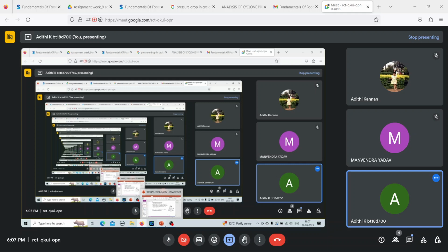So that will answer the question that is being asked here. The constant rate of filtration is given by this entire equation, where this part becomes the slope. If you put delta P on the LHS and dt by dV on the RHS, this will be the slope. That is, Kv in the constant rate of filtration is contributed by the cake, which includes mu alpha Cs by A square dV by dt. The intercept is contributed by the filter medium, which is mu Rm by A dV by dt.